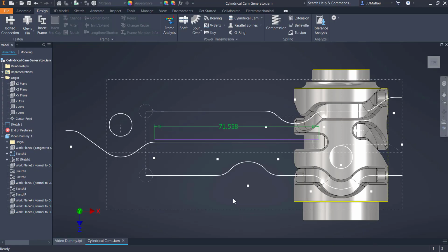One final thought on the design of cams. Normally when we're laying out a cylindrical cam like this, we specify the slot in terms of the angle going around the cam. For this distance, I have it calculated as 41 millimeters. That's the diameter of the cam times pi. That gives me the circumference, times the angle I want out of a total of 360 degrees going around the cam. And that converts that angle into a linear dimension that we can then wrap around the cylinder.